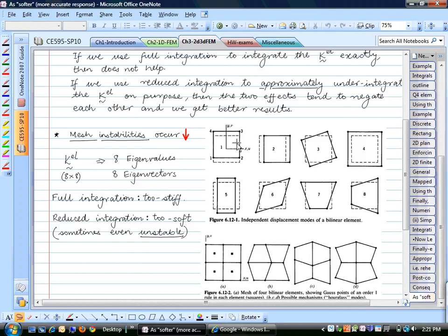And if I assemble that truss into a bigger space truss, then I just have to try to find out how many rigid body modes does this have, or how many mechanisms does this truss have. That would be the number of 0 eigenvalues. So 0 eigenvalues denote rigid body modes once again.